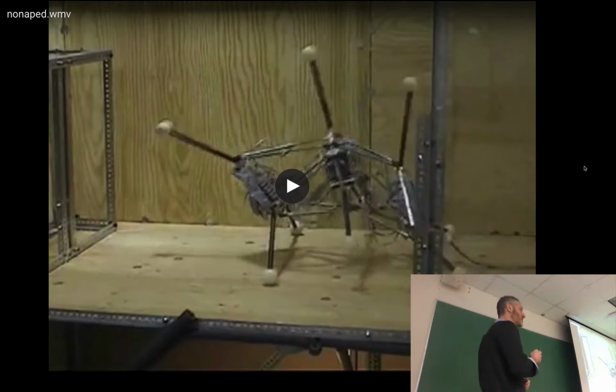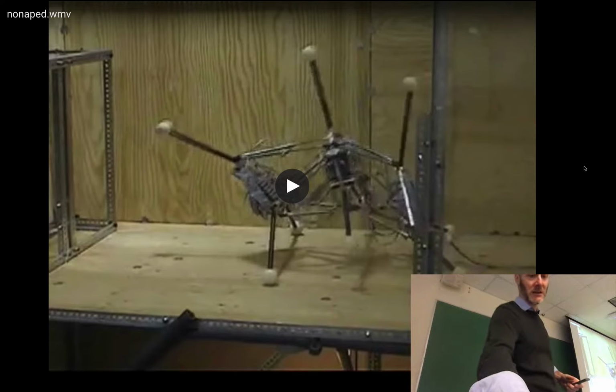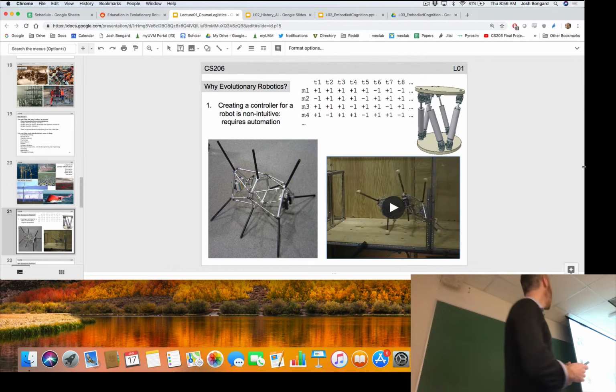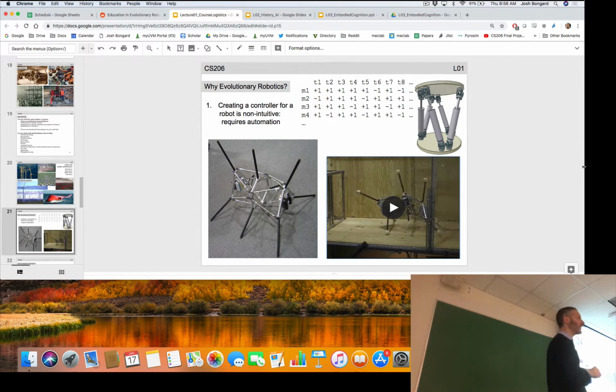Okay, of all those gaits that you just saw, is that the fastest that the nonaped can travel? I was just wondering if it ever used the 3 legs on top. Well, okay, so why the 3 legs on top? If this robot is moving downhill or flips over or falls on its side, it can carry on, right? So they're just sort of there in reserve.